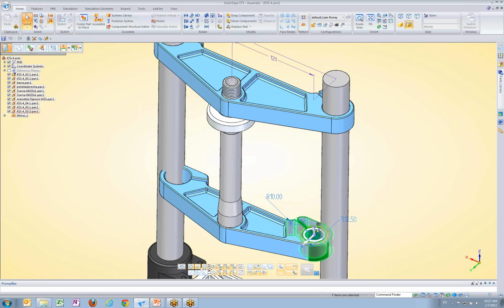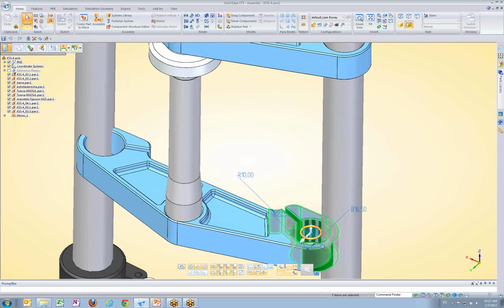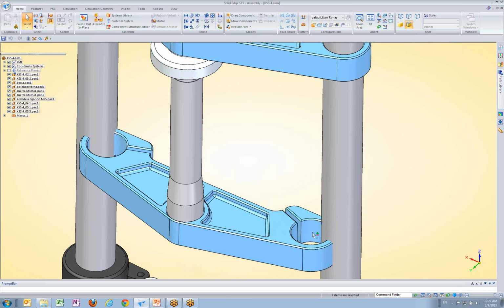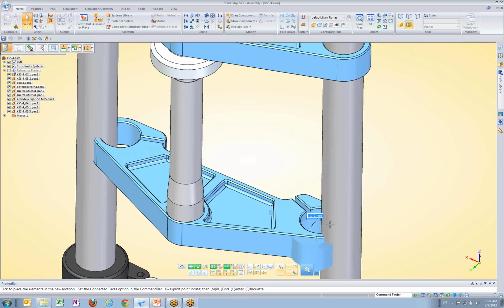I'll position my steering wheel on the top of that hole, but I'm going to be careful to make sure that I've got the orientation flat, because I'm going to use this disc in the center here, because that's a planar move. That allows me to move with 2 degrees of freedom along a plane. So if I click this, you'll see that as I move my mouse, it's adjusting that part in real time.